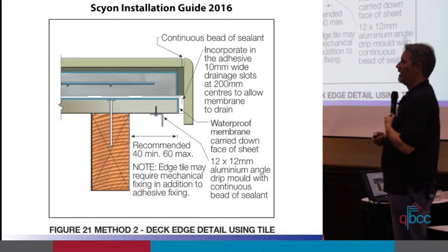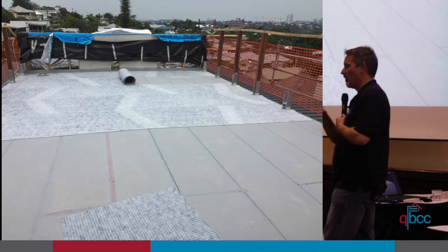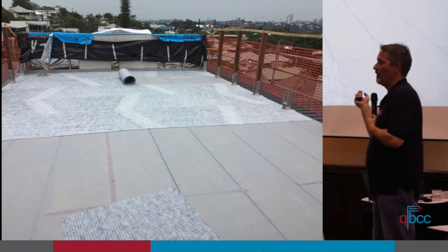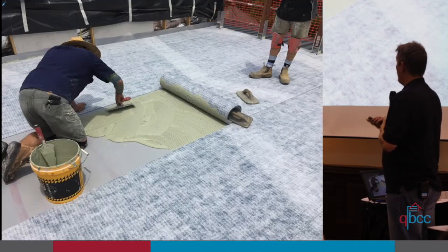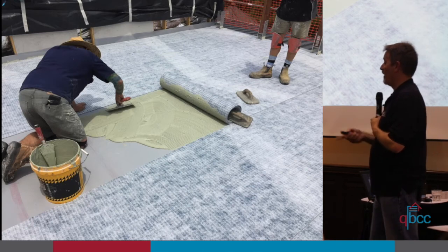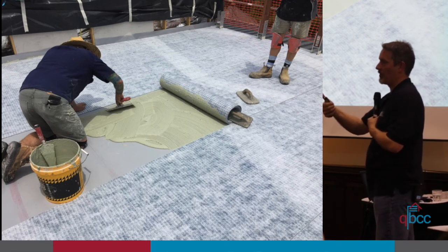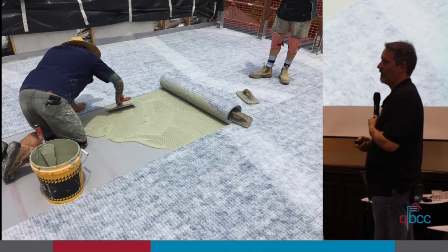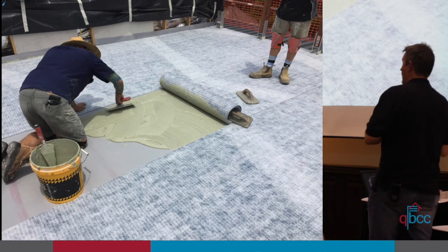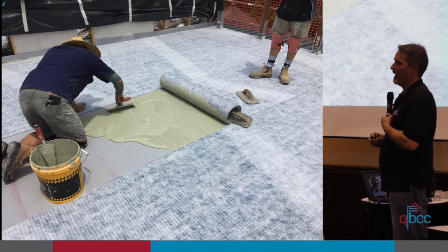All right. Other option, there's a workaround if you can't do that, and we often find that with refurb jobs, you can do a waterproof uncoupling membrane, all right, which is basically a sheet membrane glued on with, you know what that glue is, with a tile adhesive. All right, that's another option, and refurb comes into play because the engineering isn't there for the screed bed, or sometimes there's a staircase that goes on so you can't actually raise the top by 40 or 50mm. All right. When I talk about engineering, if you didn't know, 50mm thick screed is 100 kilos per square metre. All right, so it adds up.